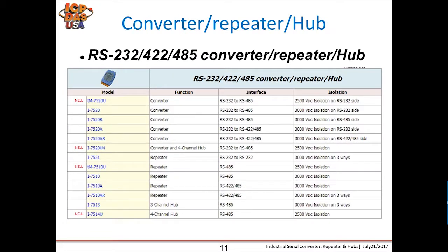Nowadays, most industrial computer systems provide standard RS-232 serial port with limited transmission speed, range, and network capability. The RS-485 standard overcomes this limitation by using the differential voltage line for data and control signal.